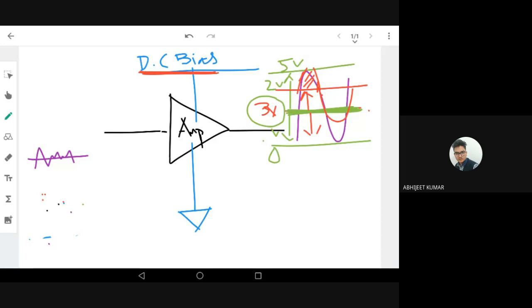So the amplifier is amplifying the input signal and the energy. It has to be given proper DC biasing. It's called biasing, where you fix the transistor operating point. Especially when you think of operating point, we are concerned about the output operating point: the collector emitter voltage VCE and the collector current IC.